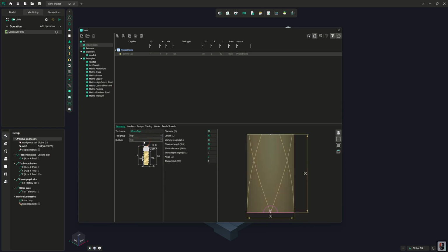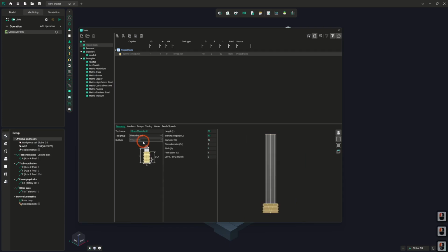We also have standard tapping tools, threading mills as well, with as many different steps in there as you need, which is obviously very, very useful to have. Mills with negative radii. Now, this is something that you'd probably see a bit more often in the world of CNC routing, although you do obviously get it in milling as well, where you can define a profiling bit. Now, you've got a fairly standard form here with just the trimmed out negative radii. It is possible to do slightly more elaborate ones as well.